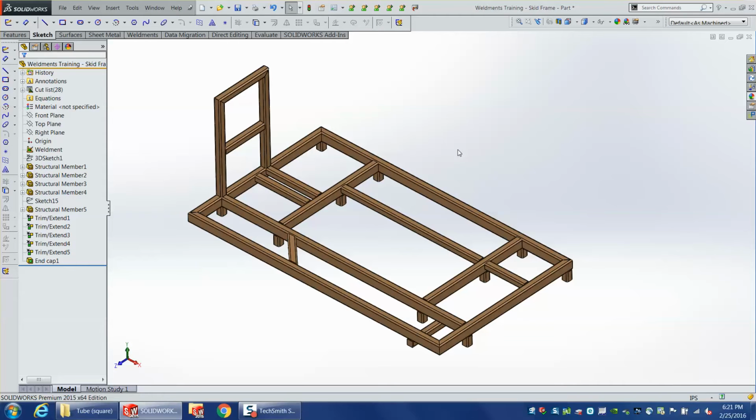So that may work well for some cases. I found that too. If you have top-down modeling in a situation where those components might get picked up elsewhere, might get used by other users and people, that's where we have big problems with that. Also, if you want the drawing, working with a PDM system, if you want the drawing to always be what it was when you release it, those are some questions you have to answer. It is effective in that.